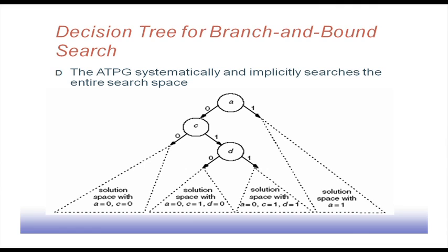After a few steps in this tree, you will find that all the paths going further are not going to lead to any test pattern. There is no variable that can be set now to lead to a test pattern. In that case we can backtrack and come back with the other option.